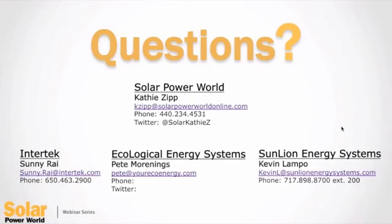So what we have noticed in communications is that power line communications, the ones that transfer over the electrical wire, have limitations on how much data they can send. It's one of the reasons why we see most of the microinverter and AC module systems limit themselves to about a minute as the fastest they can send data. And at that level, there's not enough granularity in the data to effectively troubleshoot.